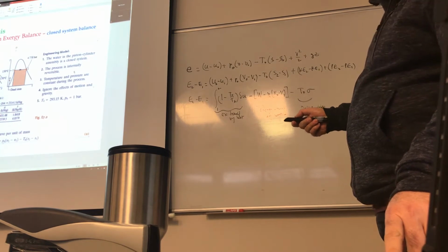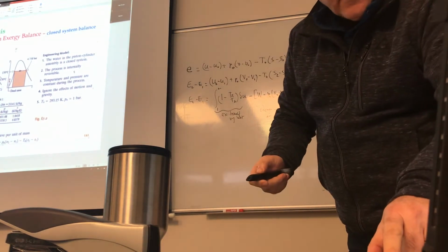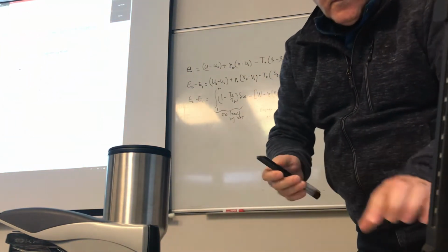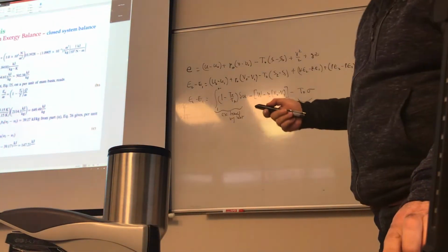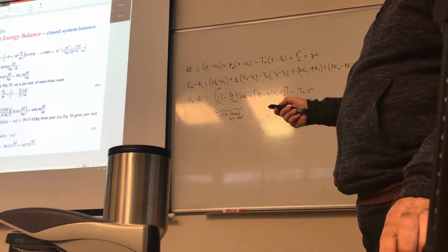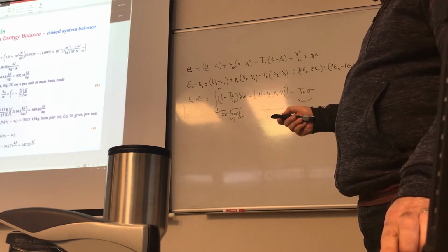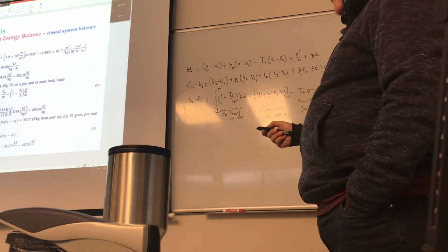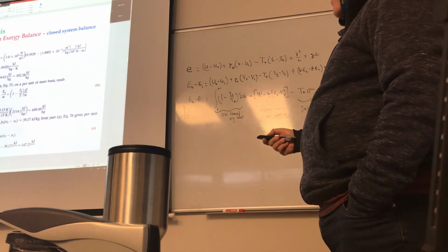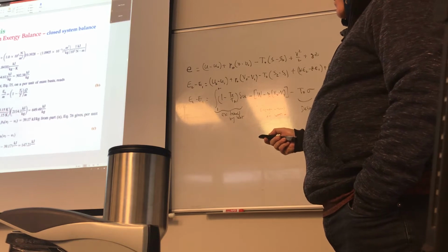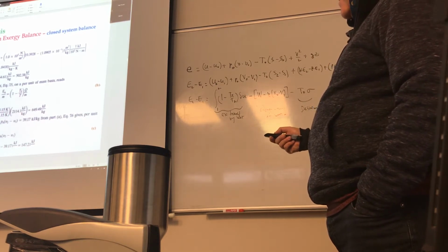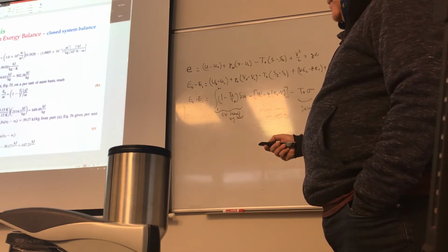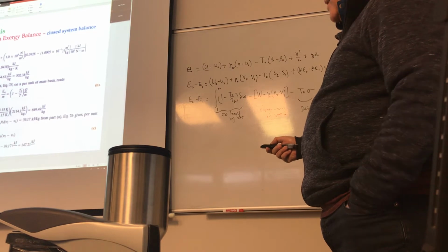Okay, so we get the exergy change that's equal to 502.38, and then evaluating the one by heat transfer, it's again looking at the equation 1 minus T naught over T, times Q over m, and the temperature, and this is the temperature T naught, and this is the temperature T, and then EW, again, it's just plugging and chugging the values.